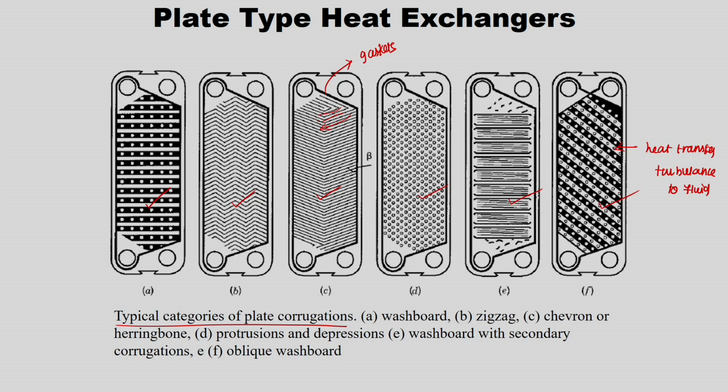As I discussed, there are many improvements made in these kinds of heat exchangers. For example, there is something called a double plate security system. That means both the plates are welded and formed as a channel. Then these formed channels are further put together in the module by gaskets, right. So, if there is any leakage between the plates, then obviously it is known, because it is kept as a channel. In that way the security system can be improved to avoid leakage of the liquid food product